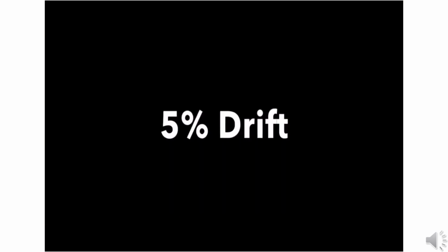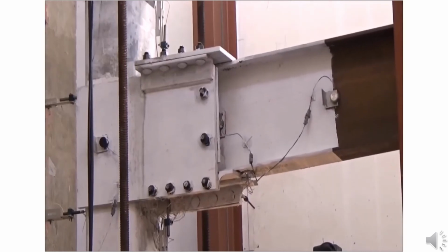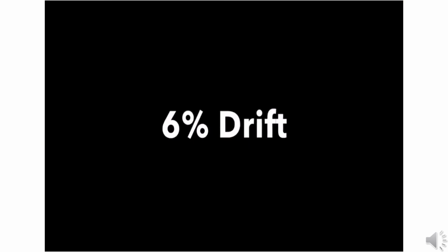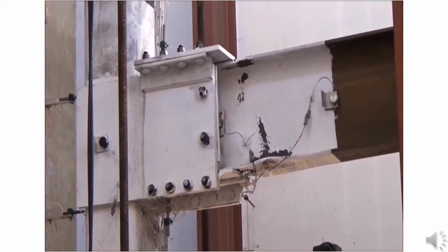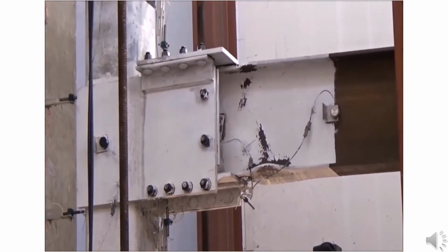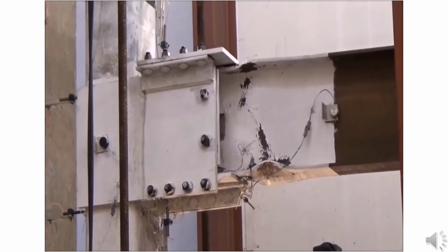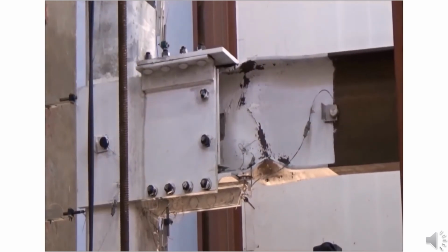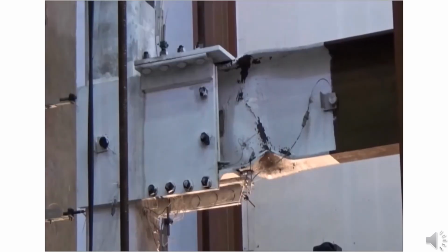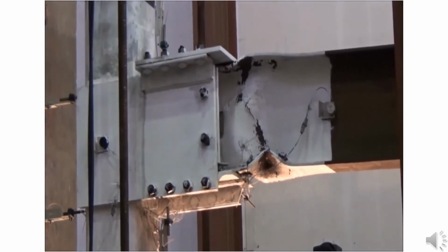Since side plate moment connections are proportioned to develop the probable maximum moment capacity of the beam, the plastic hinge formation occurs within the beam. The side plates, in particular, are designed to develop a moment capacity larger than the plastic moment capacity of the beam. This is done to push the yielding and strain hardening towards the protected zone of the beam.